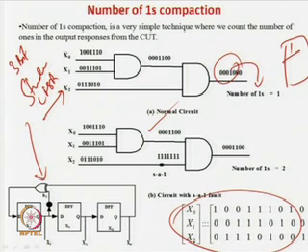So, for all cases, if you apply here 1 0 0, in the normal case the answer should be a 0. In the normal case it should have been a 0 over here as you can see. But now it is the stuck-at-1 fault, so every time it will be a 1. So, we will have seven 1s, because in the series of test patterns, 1 2 3 4 5 6 7 test patterns are applied. In this case every instance will be a 1 because of the stuck-at-1 fault.